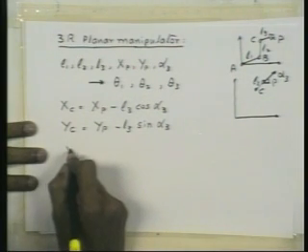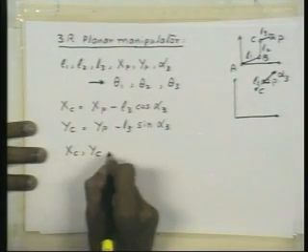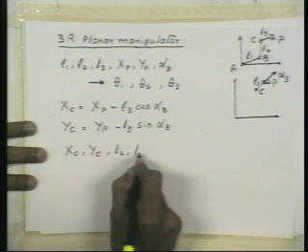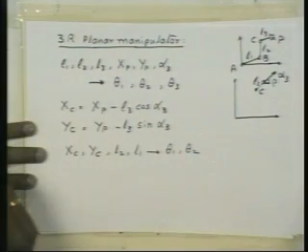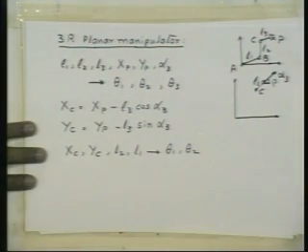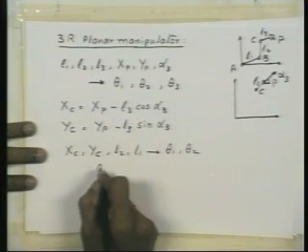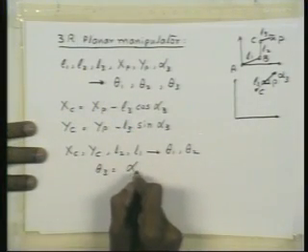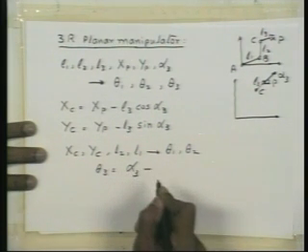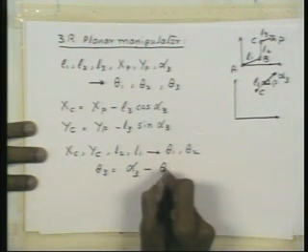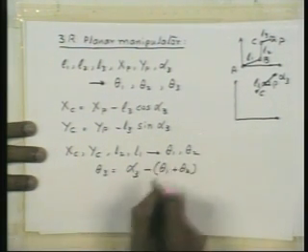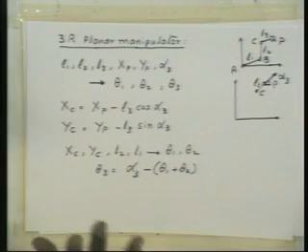Fine. So from XC, YC, L2 and L1 we can calculate theta 1, theta 2 as we just now did, right? And theta 3 is nothing but alpha 3 minus alpha 2, right? And alpha 2 is theta 1 plus theta 2. Fine. So it's as simple as that.